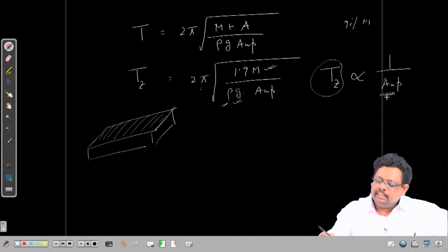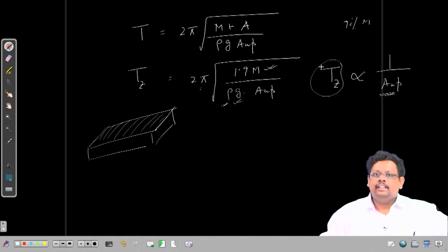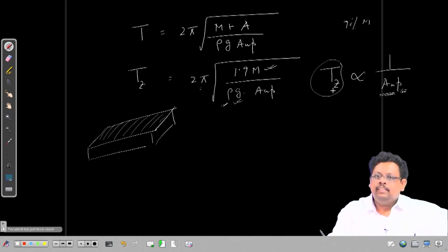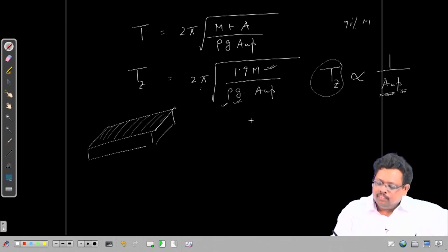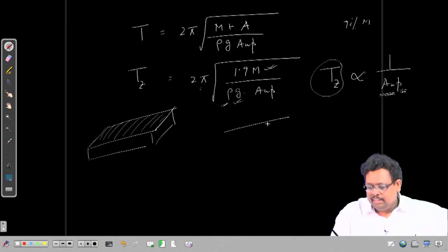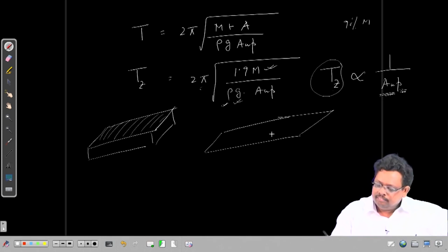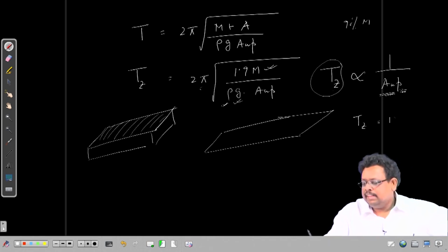Now, you see this is totally different from the hydrostatic thing. Here you increase this, then the natural time period will decrease. Let us say in a normal situation you have this barge a little bit slender, then the natural time period T z becomes, let us say, 10 seconds.